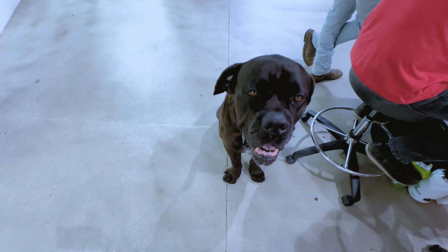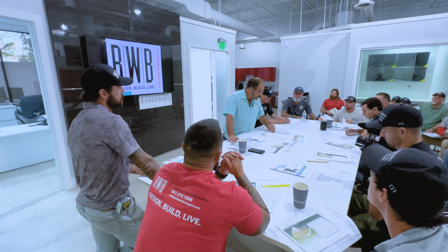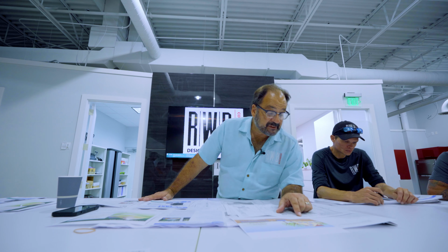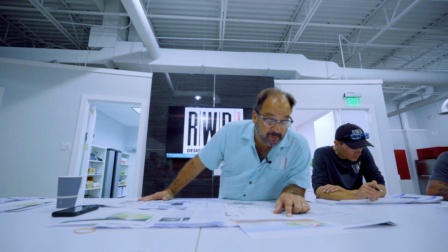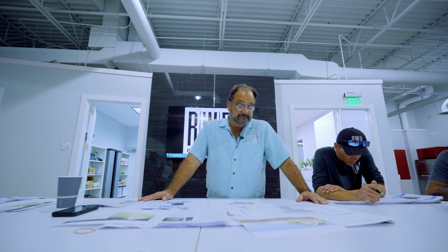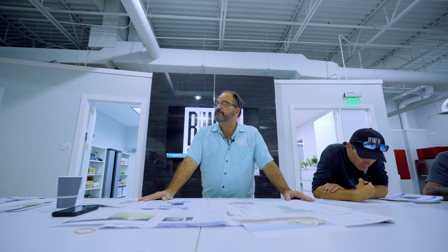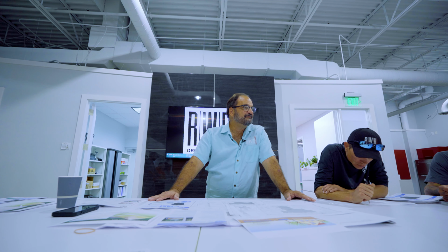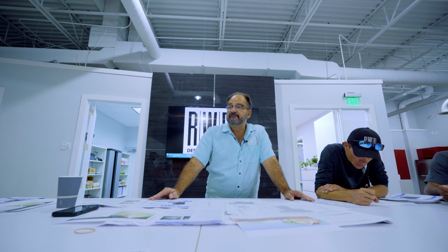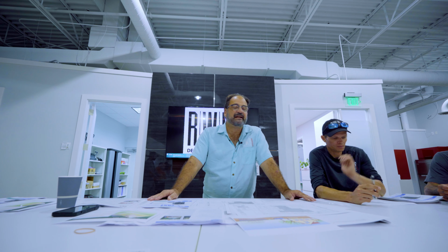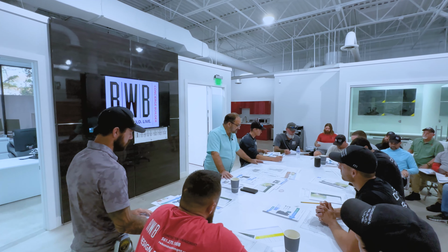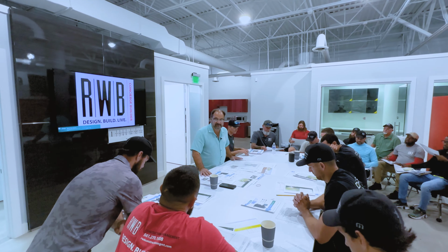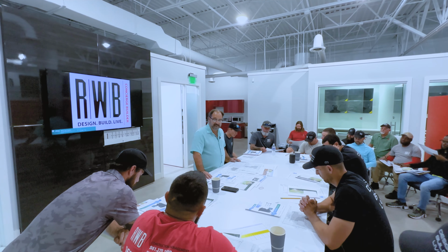On this plan, for example, if you look at the north wall, the neighbor's property at one point is at 22 feet high. The driveway is at 11, which means the bottom of the footing is at 10. Okay? That means I have a 12-foot cut straight down that I have to make. Nobody thought of it. Okay? You're building it. You have to think of means and methods for everything you do. You have to look at that and say, how am I going to build that? Not just let it go until it comes to bite you in the butt.